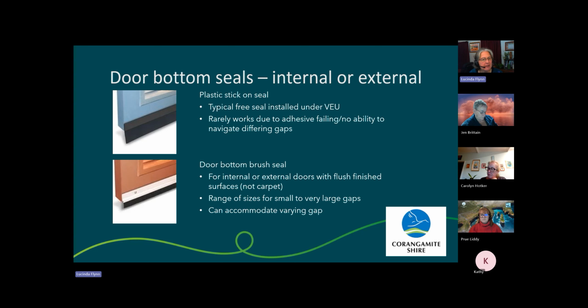If you don't, then a door bottom brush seal, this one, is not a bad idea, and they're a lot more flexible to little changes in the depth of the tread or changes in the gap because they're brushes. And so they just mold better around what's going on, but they're not for over carpet. You can also get a very big range of sizes from small gaps to really big gaps. You can get super long brushes. So if you have a massive gap, that might be what you're going to need to do.